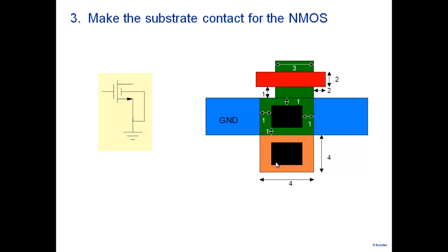And this is the region where I do contact. And you are not seeing it, but we are extending this metal that you see here, blue. You will not see it. The metal is extending here also. So this metal that you see here is extending all the way like this and coming here. This is where I have P plus also. And this is where I have the contact also. And thereby I've made a contact to the body. Body is P type. And I created a region P plus. And I made a contact here. And this region is covered with this metal here. And thereby I've made a contact. Yes?